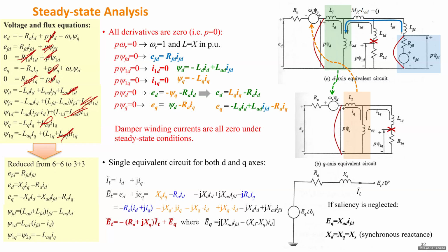So for the exciter control, to change the terminal voltage, we utilize a feedback control system based on the gap between the terminal voltage and some reference value. You can influence the field current. By changing the field current, you change the EQ. By changing EQ, you can change the ET. So finally, you can stabilize the terminal voltage at any reference value. So that's the idea of exciter control.